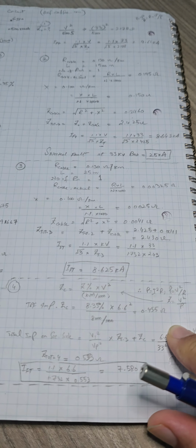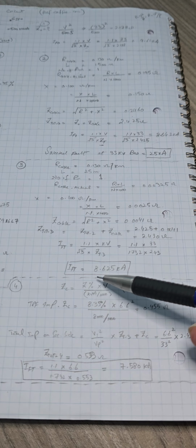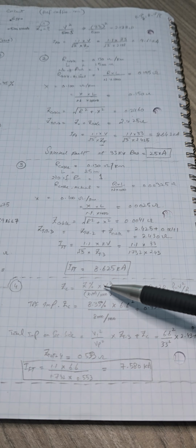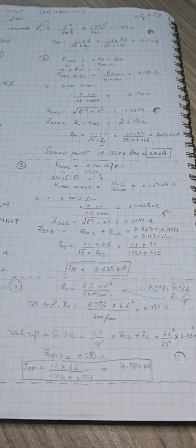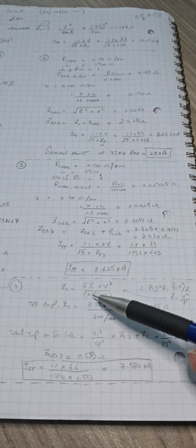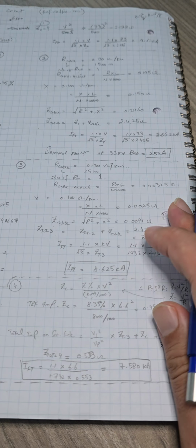Okay, here we go. The impedance value of the step down transformer is the percentage multiplied by the voltage square divided by kVA divided by 1000. How we can remember this formula is using simple Ohm's law: V square over P, like kVA, what is the rating of the transformer, and then the impedance percentage of the transformer.